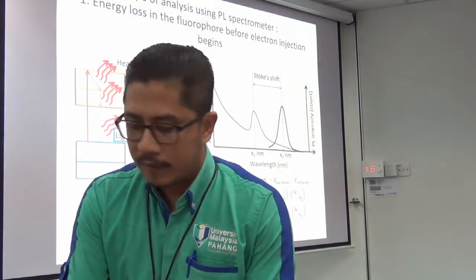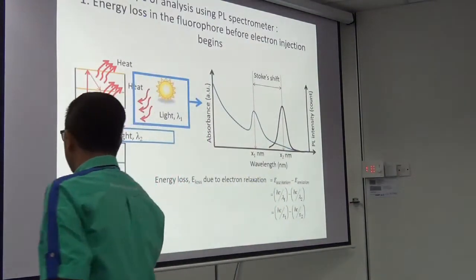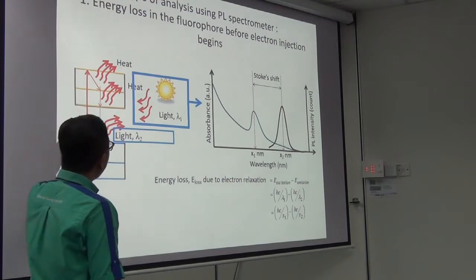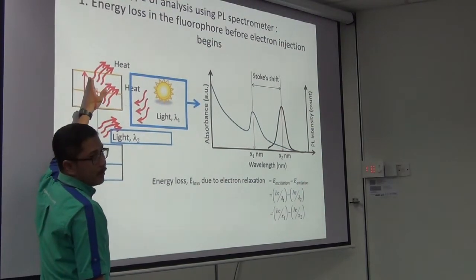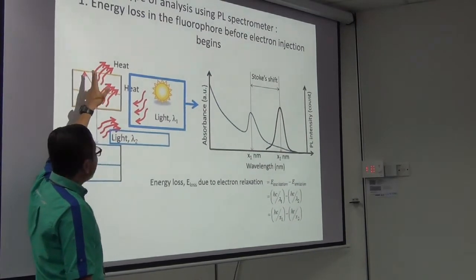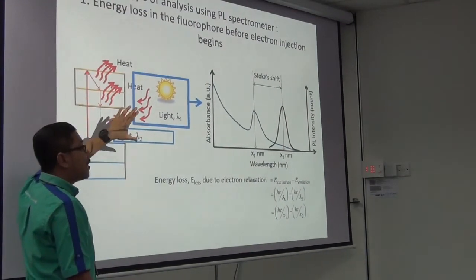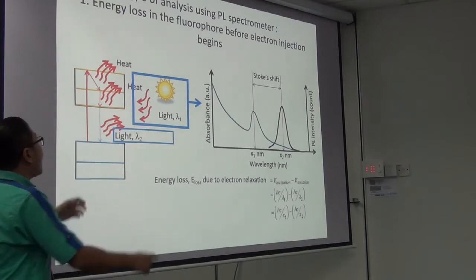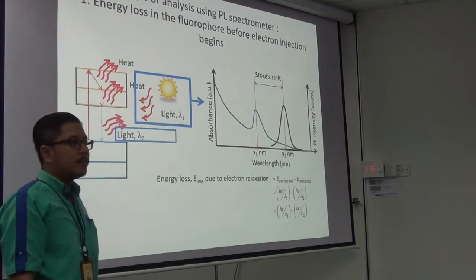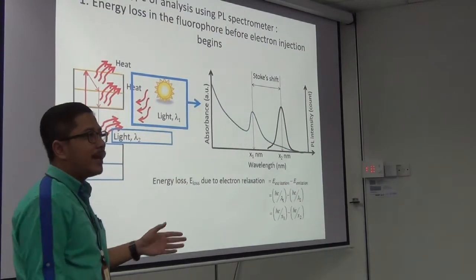Because energy loss is very crucial. In solar cell technology, we want to maintain the energy of this electron. If possible, we don't want this electron to lose any of its energy. Electron over here, we should pair with another semiconductor type, and that electron should be transferred to the neighboring semiconductor, so that the electron will flow without losing its energy.